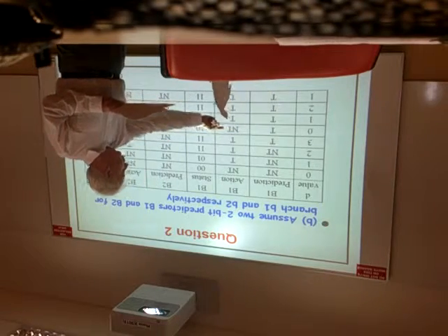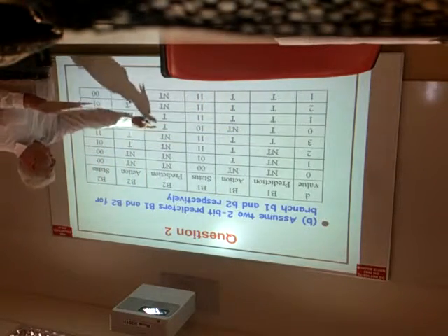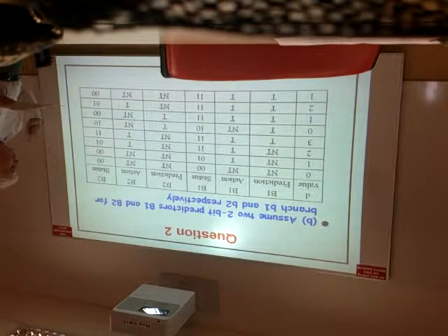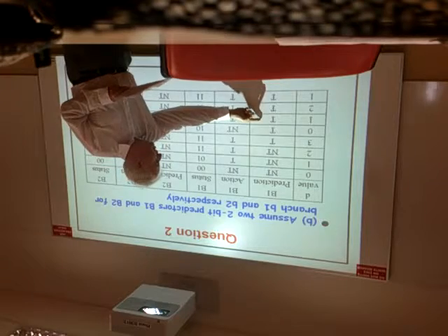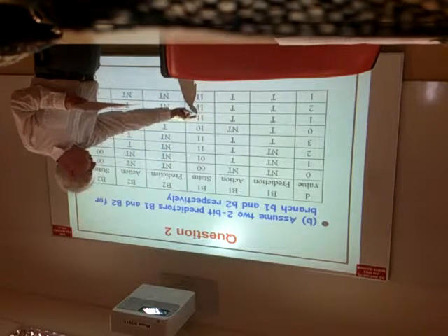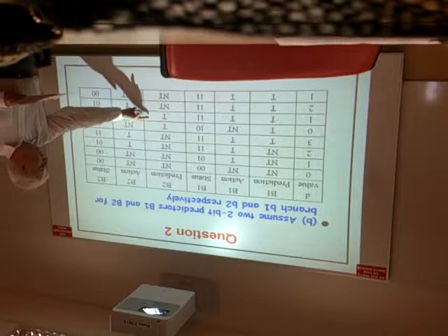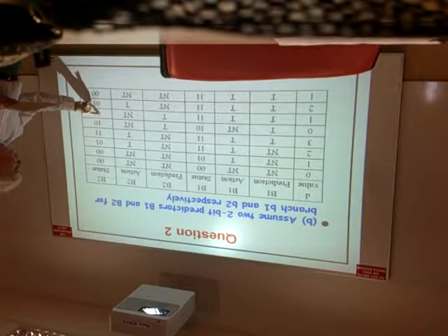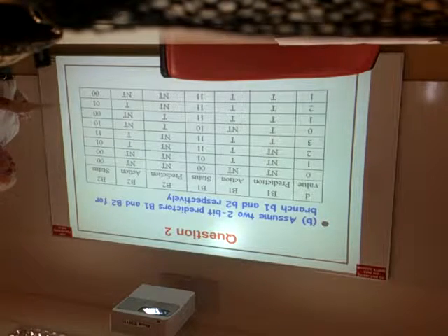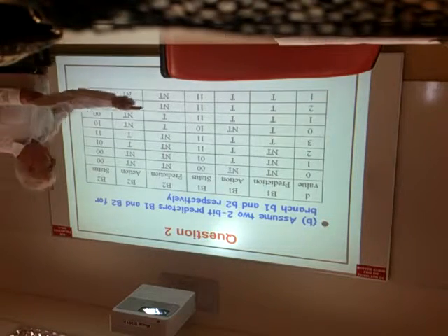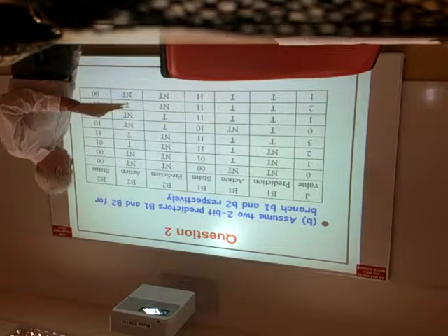Here, predict taken, not taken, so we go back to 1, 0. And similarly here, predict taken, not taken, go back to 1, 0. Here, still predict taken, it is taken, so we change the status to 1, 1. And here, predict taken, but it's not taken, so we change the status to 0, 0. Okay, and here, we predict taken, it is taken, stay 1, 1, and so on.